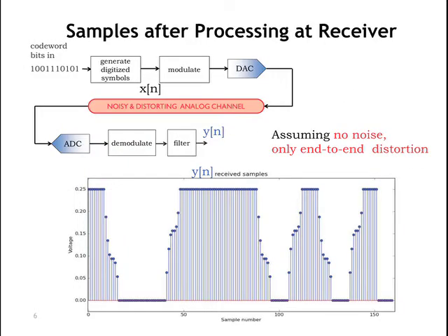And at the other end, after you've done your transmission through the channel and you've demodulated and filtered, you get a sequence which ideally is a replication of the sequence that you sent in. It can have a scale factor. Scale factors don't worry us. In this case, you see that the amplitude is divided by 2. But basically, you see the trace of what was sent at the transmitting end. There's some distortion that's introduced by the dynamics of the channel, and we'll be talking about that in more detail later. So we aren't getting quite the straight edges. But after a brief transient period, the waveform seems to settle to the constant value that we had at the input. Okay, so this is our received set of samples.